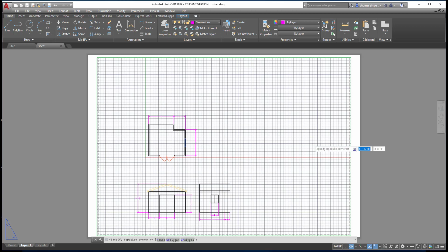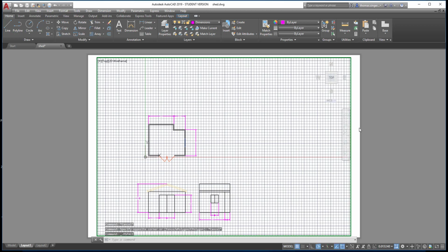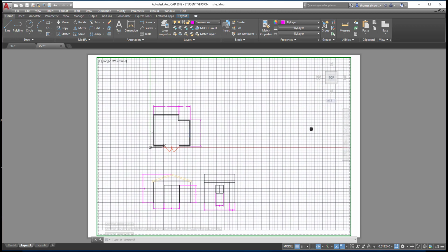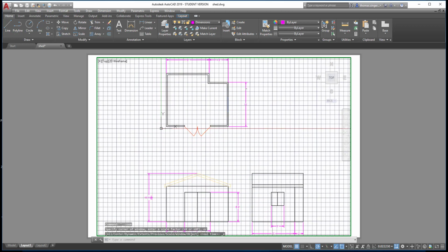So we double click in, we can double click out. And as long as we double click out somewhere outside of the green box, we double click off the viewport. If we double click inside, I can use the pan command and move it all about. And you can do the hokey pokey from there. Which also means that I can double click inside on the wheel, and now it does a zoom extents. And so that zoom extents maximizes the printable and viewable environment.